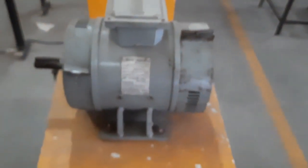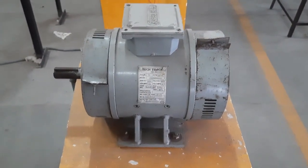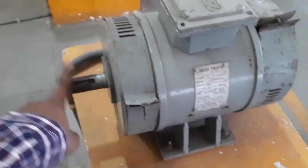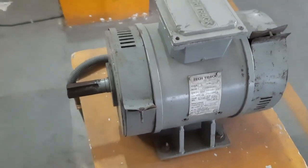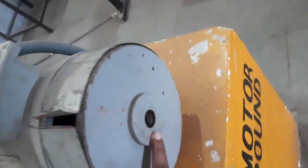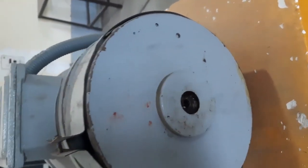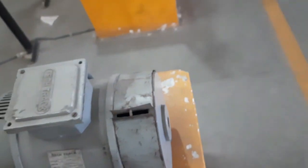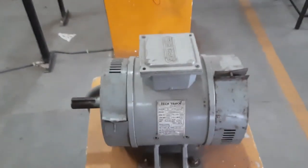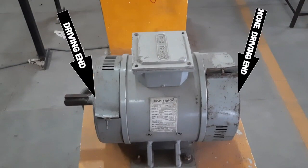Now before moving forward, I would like to tell you two major important things. This is named as your driving end, where you connect the turbine or your load, and this is known as the non-driving end, where you will connect the tachometer to measure the speed of that particular generator. Generally, in any DC machine, bearings are used at both ends, the non-driving end as well as the driving end. Both ends will have bearings in order to reduce the friction.